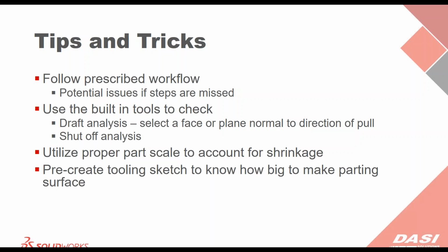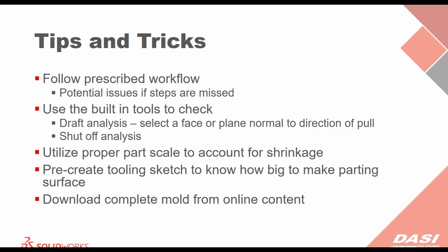Now you can go back and adjust this pretty easily. If you forget and create your tooling sketch later, you can go back and adjust your parting surface, but that is a pretty common error that I see, where people put that parting surface in, they just leave it as the default or really small, then they go on, they create their sketch, and it gives them a warning or an error saying that it cannot create their tooling. It's because they didn't make their parting surface big enough to encompass their entire tool.